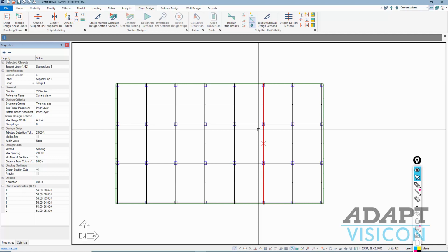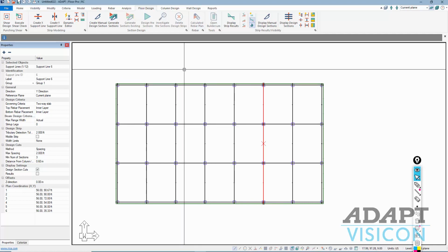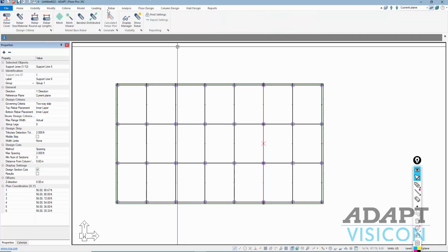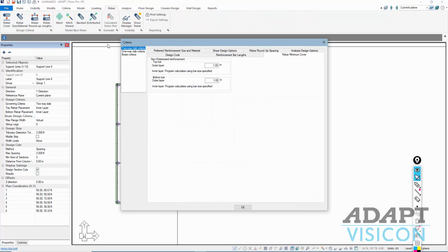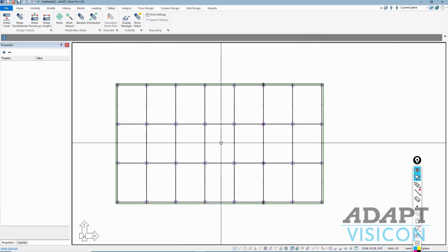These are being designed as RC slabs. One such characteristic might be cover. In the rebar cover, we want to go ahead and define that. So under this rebar cover option, for a two-way slab, we're going to say the cover, and this is from extreme fiber to the face or to the outer edge of the reinforcement. We'll say this is 0.75 inches for this two-way slab criteria.